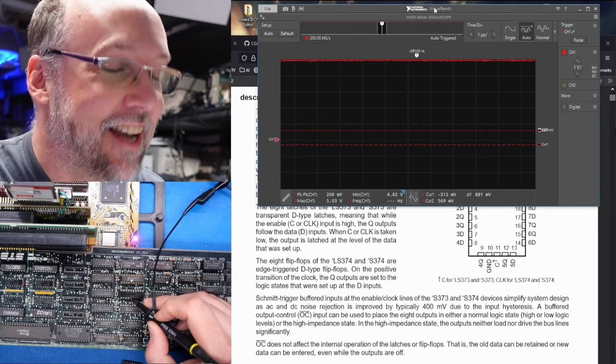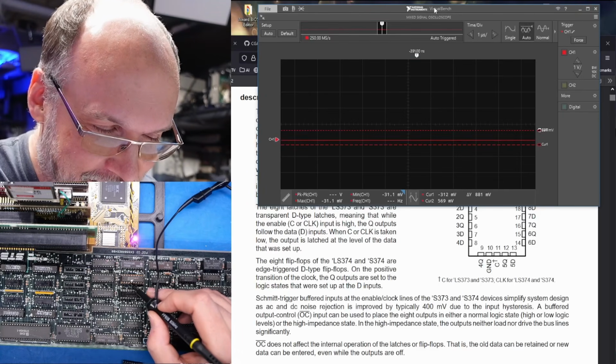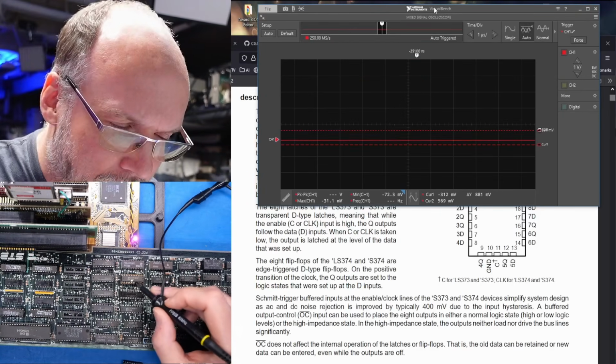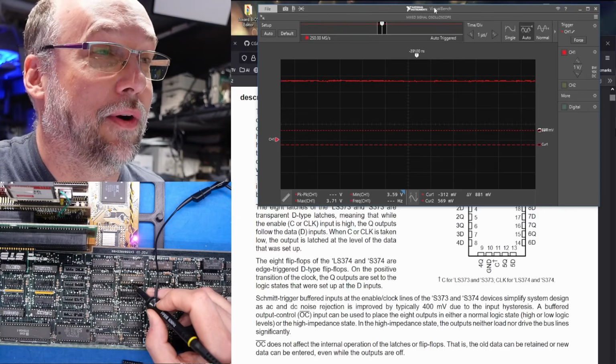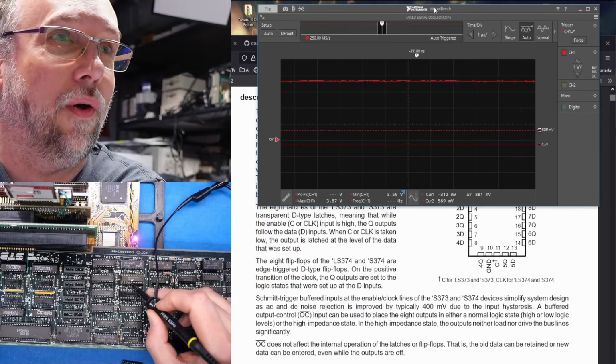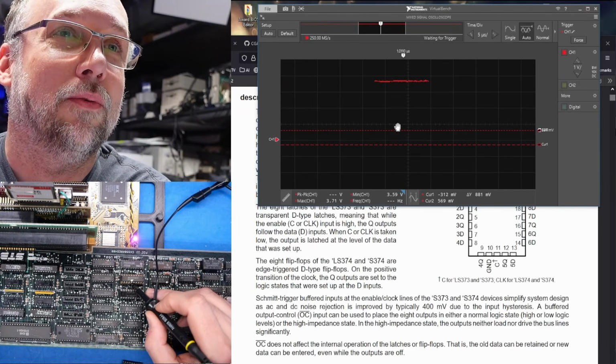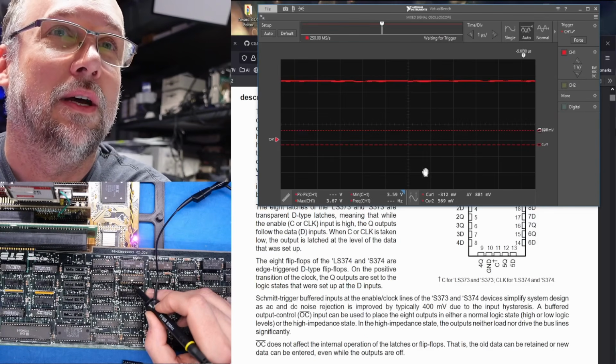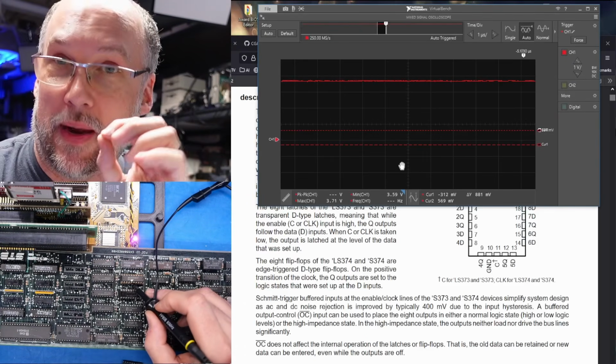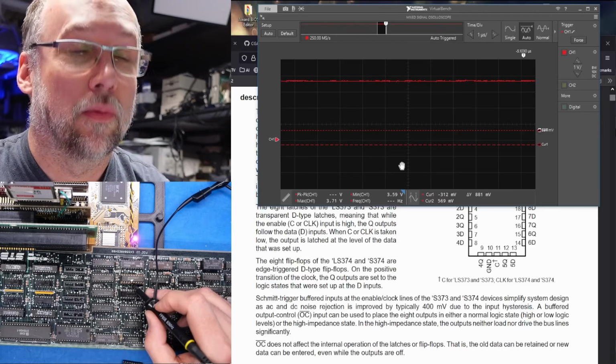And we weren't seeing anything weird. Let's take a look at the output of this IC, and that is not stuck at ground anymore. It's up at 5 volts, which I think is exactly what we should be seeing. Because remember when it was pulled high, when we pulled the chip out, or we had the leg bent out, we were seeing the normal colors.